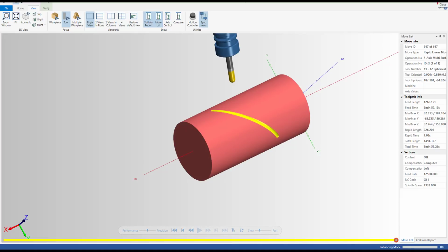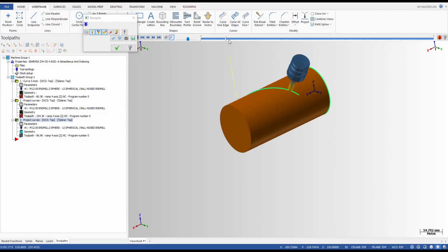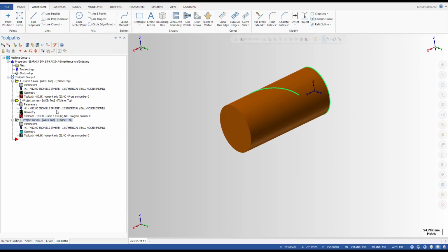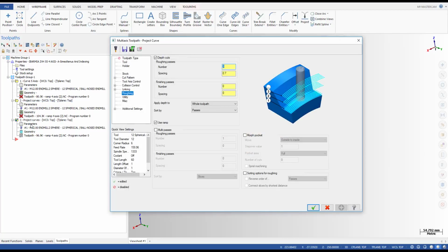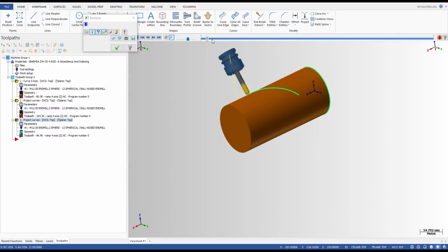Yeah, very simple. You can see I already showed you how we can create a multi-axis ramping on a closed contour. Very simple, very fast. Okay, you are unable to do it if you are not using a trick. Yeah, at least I think so. If you have another way without using the trick or tip, just show me. I will share it with everyone here.